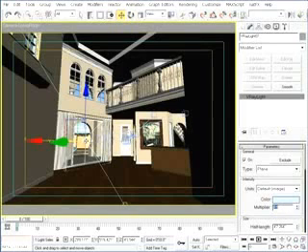But I made it a little bit more than the 5 that I assigned to the second set of lights because unlike the last set of windows that I placed lights in, this opening has a lot of extra skylight coming in because of the direct light bouncing off the pool patio. So I gave the intensity of this light a value of 7.5, which is a good amount right in between the last two sets of values that I assigned the two sets of lights.